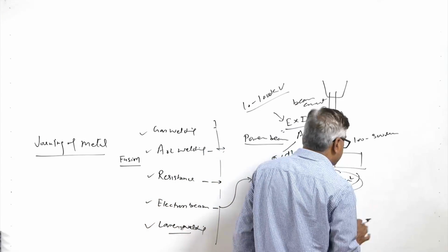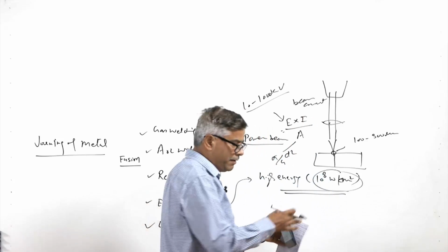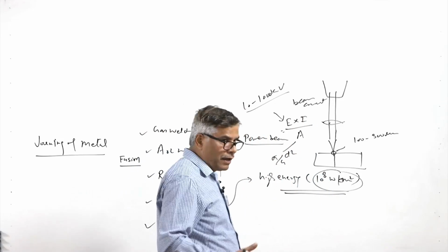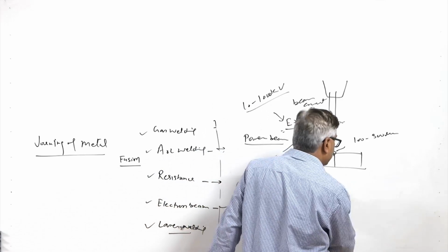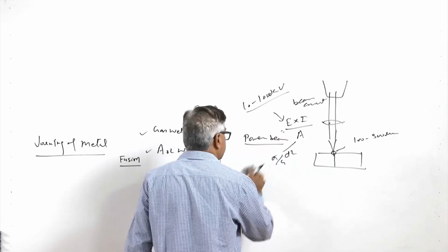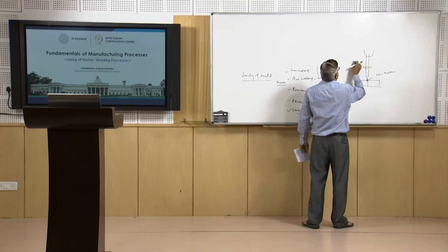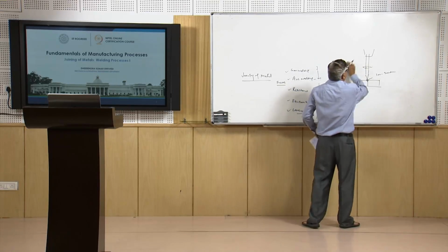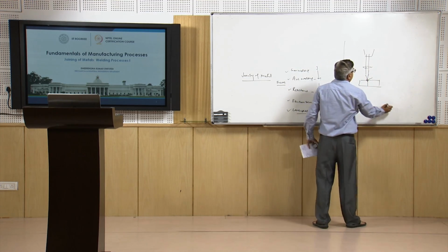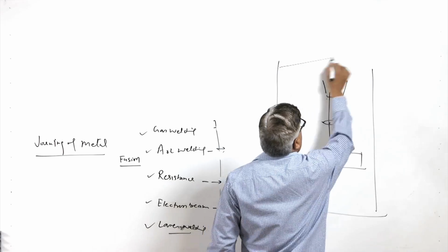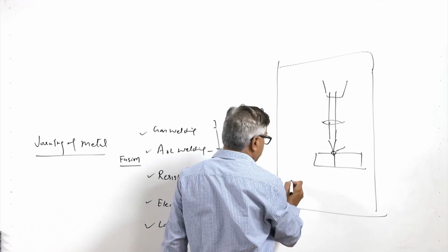Since the beam consists of electrons, when traveling through the air they collide with the atmospheric molecules, and their speed is very adversely affected. They lose their energy in the course of traveling in atmospheric conditions. So, it is always preferred that electron beam welding is performed under vacuum conditions. The entire system of the beam and the workpiece travel system is enclosed in the vacuum.